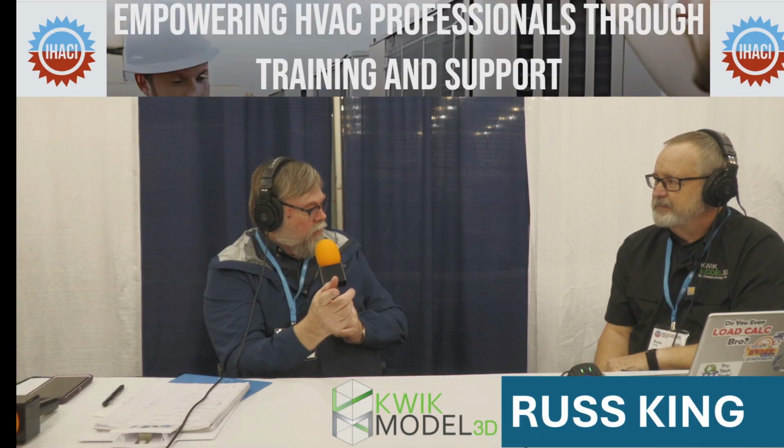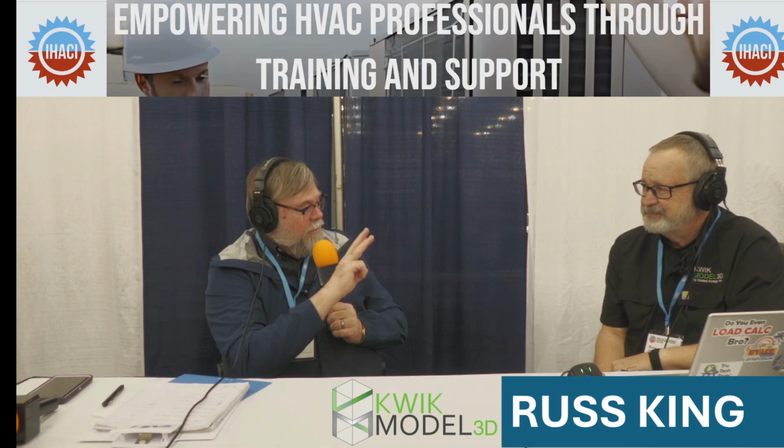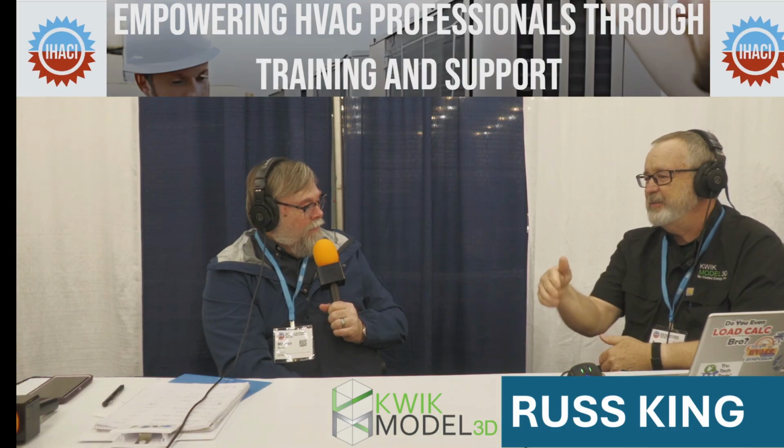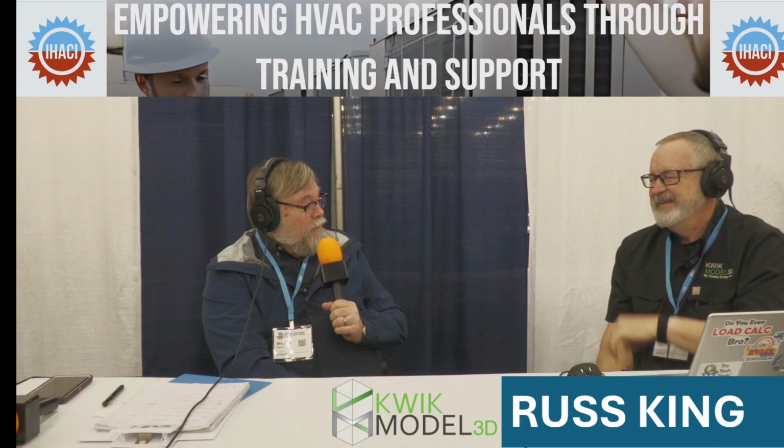So like this last one we did. We've got a guy over in Manteca. He's got a 5-ton unit, 2,300 square foot house. I think the company changed it out a few years ago, 2006, put in a 5-ton. It probably had a 4-ton before. We did his load calcs. He only needs 3 tons of cooling. So he probably has 3-ton ducts. He has a 16-inch return. It's not even a 3-ton; it's a 2-ton. So 2 tons of ductwork.